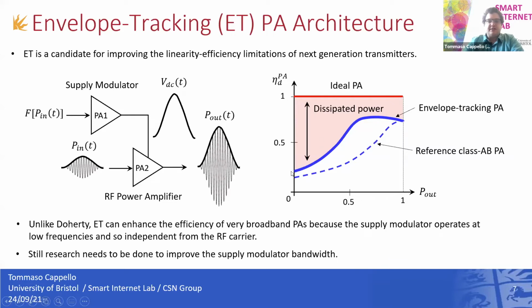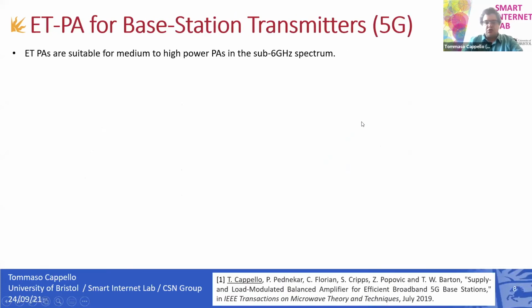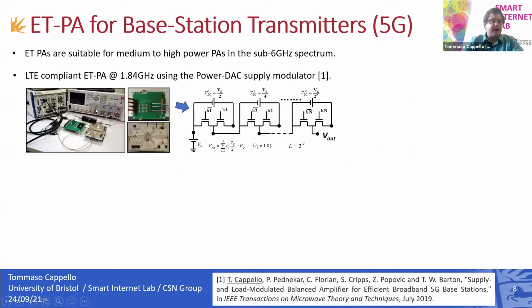A typical PA presents a backoff efficiency with this blue trace. And so the improvement compared to the same PA without ET is between the solid blue line and the dashed blue line. So by applying ET, there is a significant improvement, especially in the backoff region. So it's a very interesting approach. And so this has been, for example, applied to...